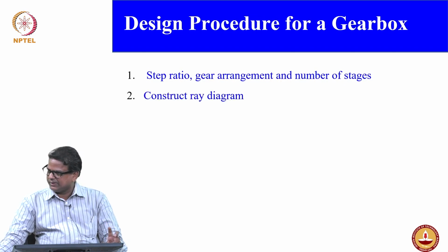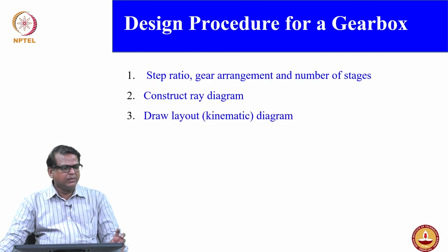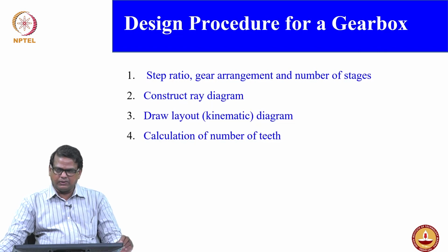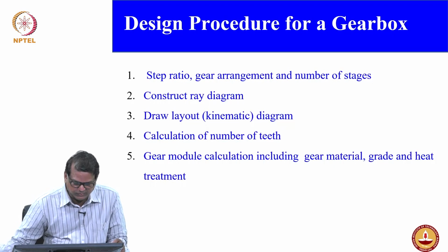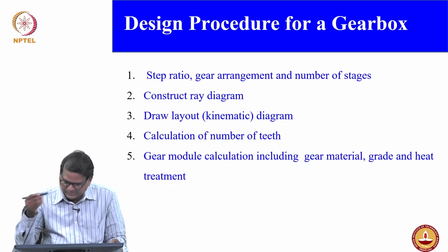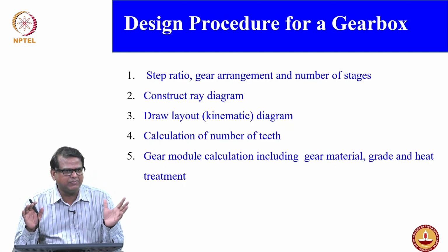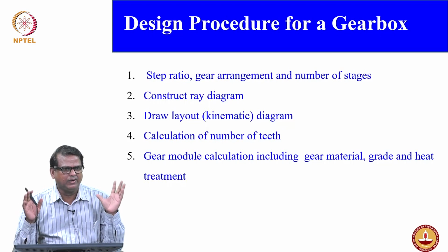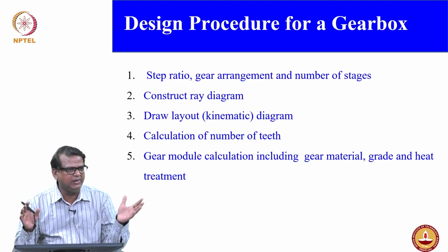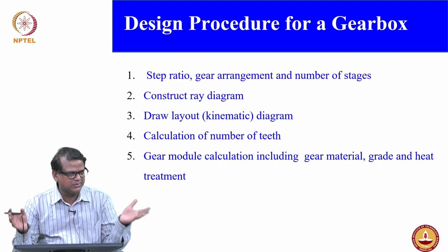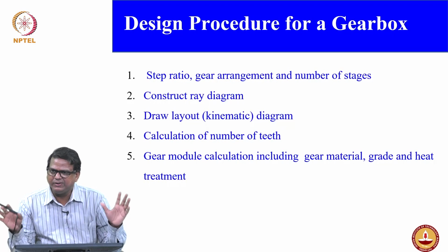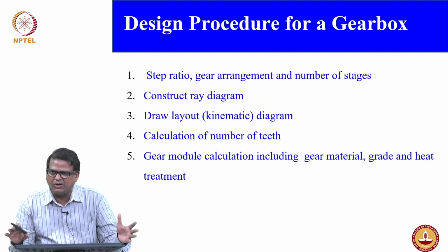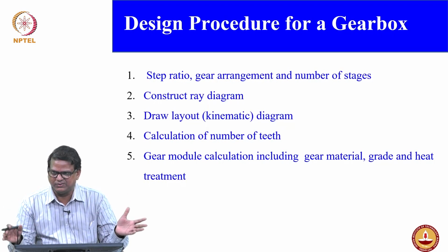Second, construct a ray diagram, draw the layout for the kinematic diagram, calculate the number of teeth, then find out the gear module. We are talking about, as a design engineer, no information is given. You know only the engine specification. Normally in automobile gearbox design, we will fix the engine power and torque.